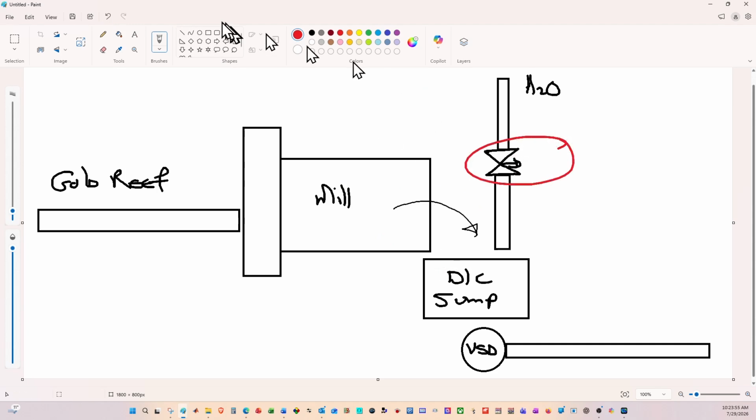Now we've also got a water valve, so that if the density becomes too high, we can add water to lower the density, or if the density is too low, we're not going to add any more water to it. We've also got a variable speed drive at the bottom that is going to control the level inside the discharge sump itself. So that becomes ideal for an MPC controller, which I'd like to go and add straight away.